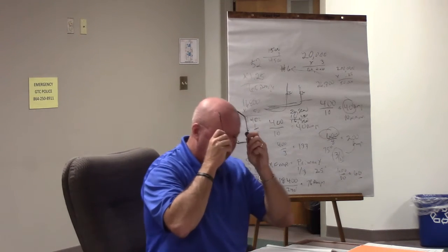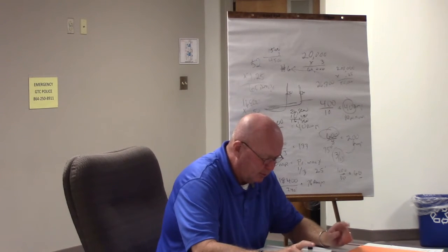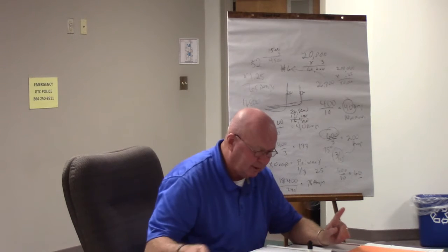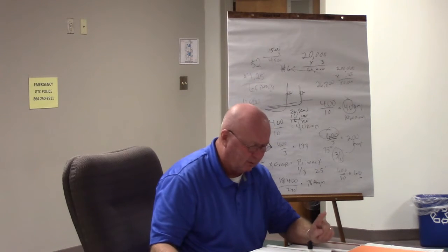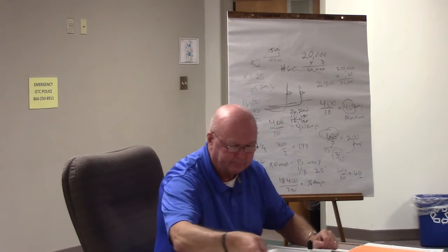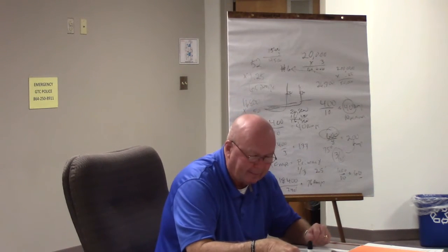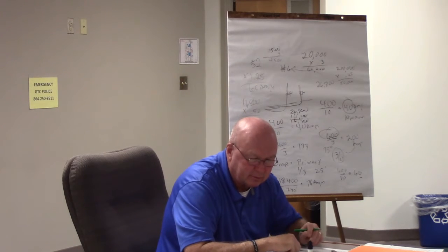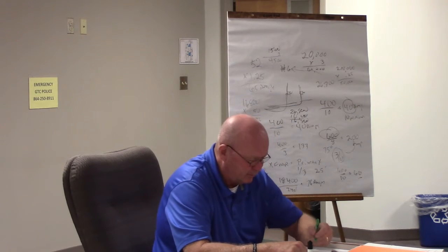Let's look at our 4 questions and we'll call it a night. Number 1. For NEC 310.15(B)(3)(a), the ampacity of 15 current carrying conductors must be adjusted by what? We've got 15 current carrying conductors. What do we have to adjust by? 50%, C.